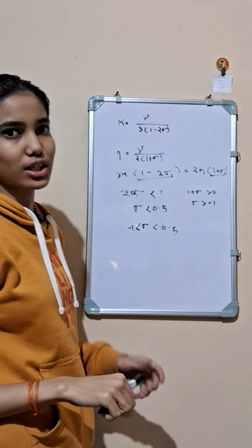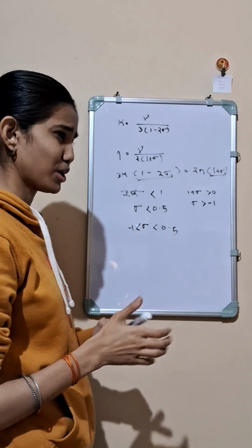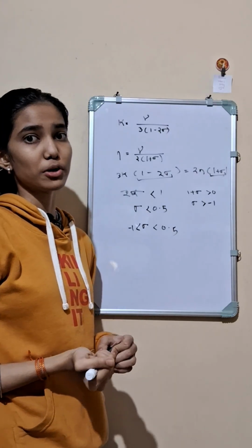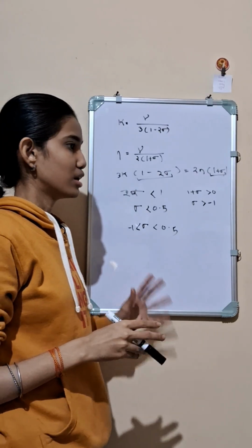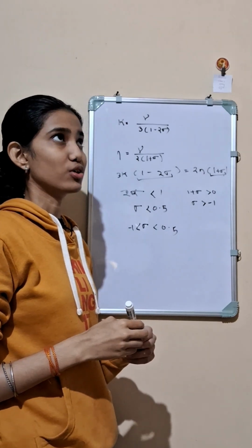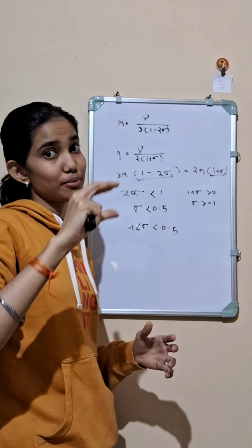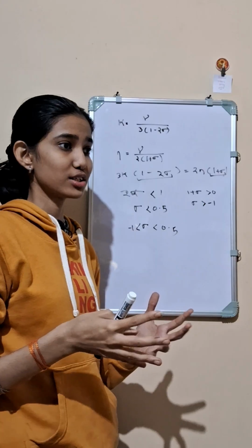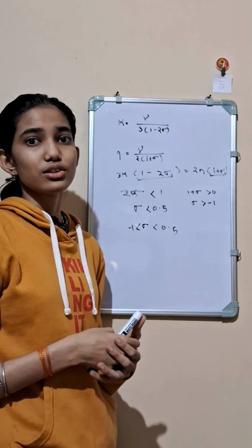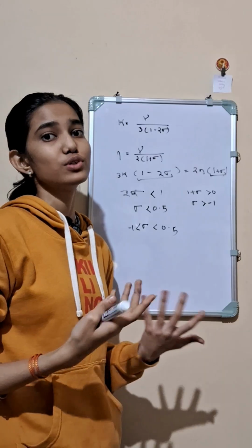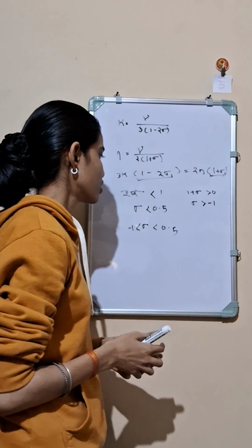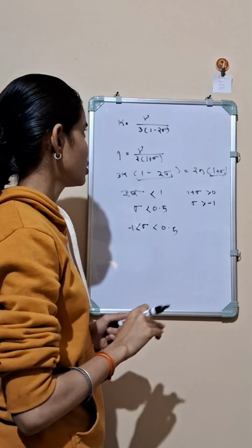In actual cases, sigma of most materials lies between 0.2 and 0.4. And sigma is a pure number, because it is strain by strain. As strain has no unit or dimension, strain by strain will also have no dimension and no unit.